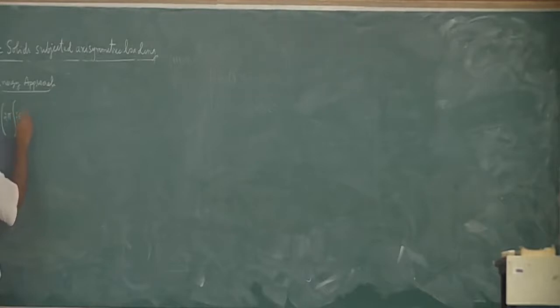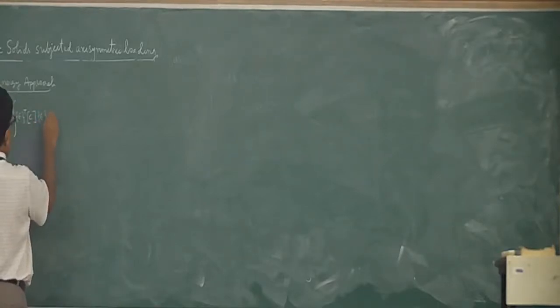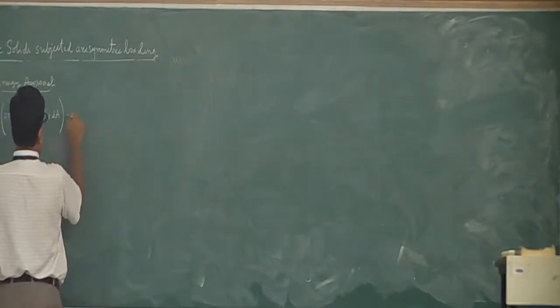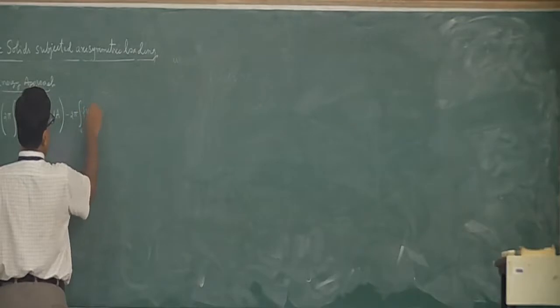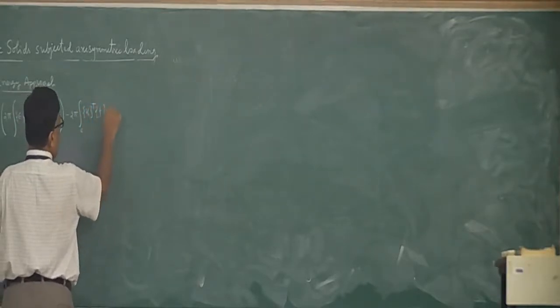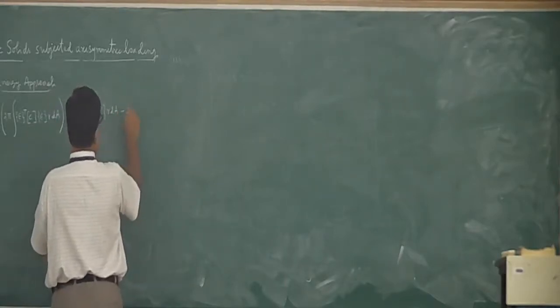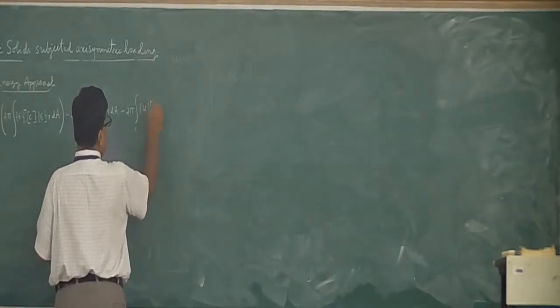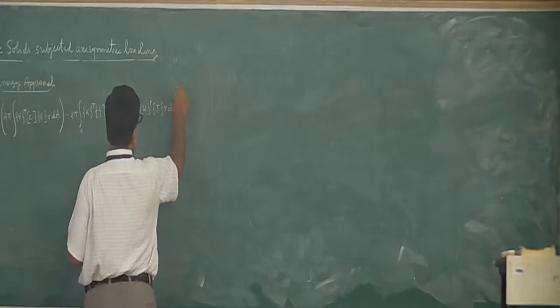I will substitute sigma as epsilon transpose C epsilon, and this one into R dA, minus 2 pi integration over the element Q transpose F R dA, minus 2 pi integration over the element Q transpose T into R dl. So this ends the integral part of that.